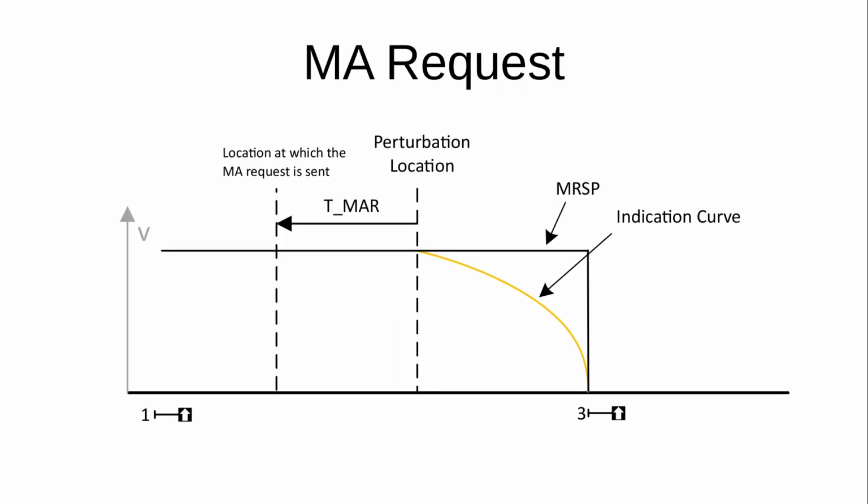The MA request is sent prior to the end of the MA, so the RBC gets to know that it should send an extended MA to the train so the train can proceed unhindered. There are also MA requests for other reasons. The graphic shows how the MA request works from SRS 360 onwards.